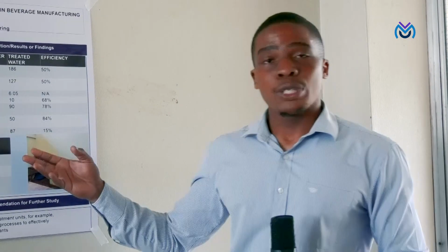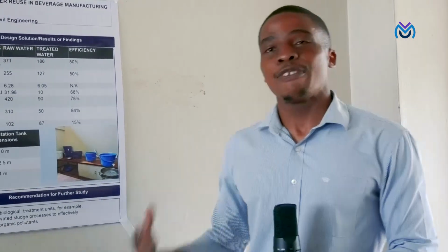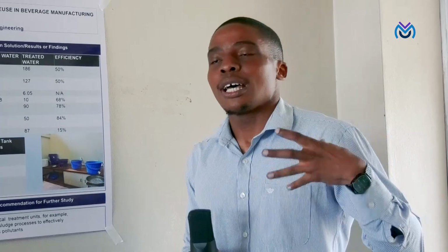In terms of challenges, for the BOD, you can see that the efficiency was only 15%. And the challenge comes in, as I said, is that we didn't use an aerator, and the only reason we don't do that is because of the cost issues.